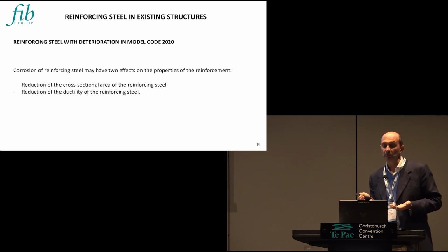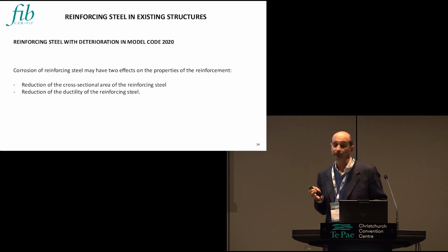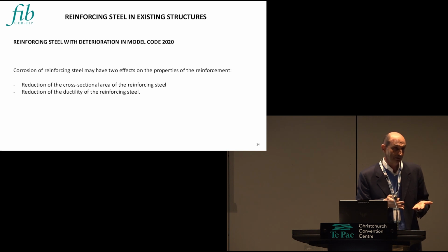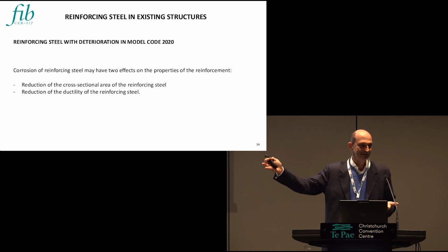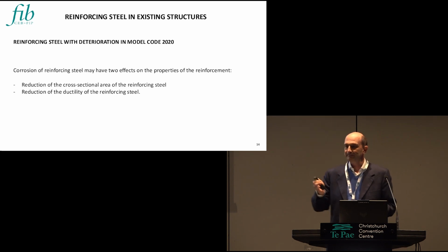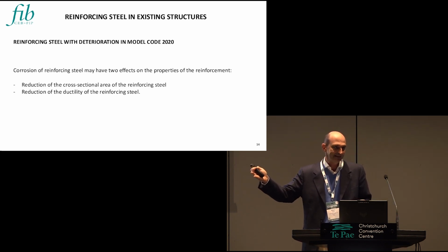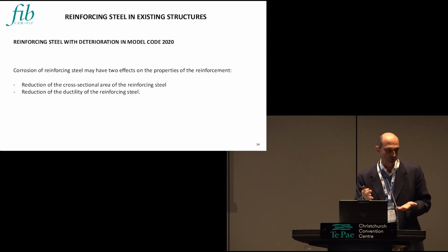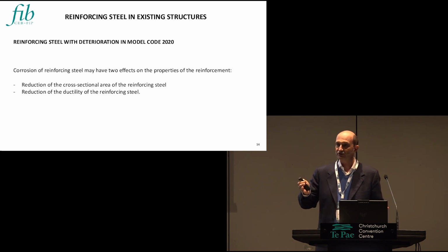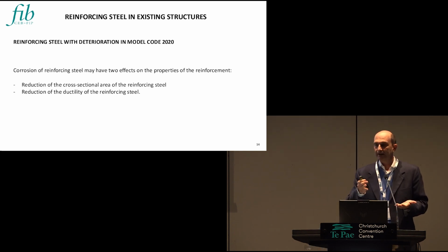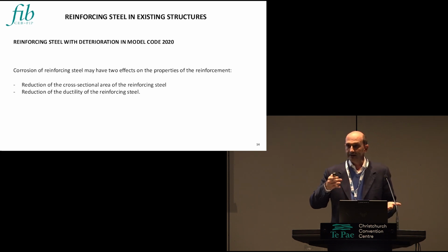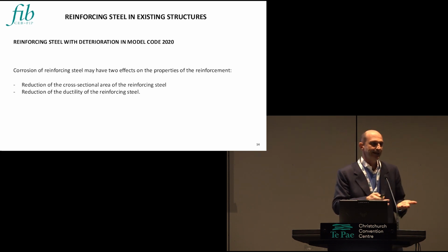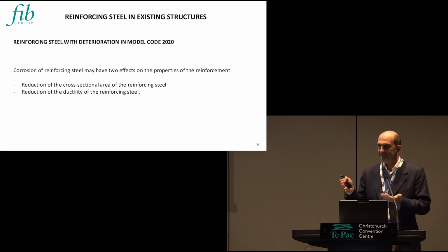And we think in a section that if we reduce the area of the steel, we have an increased ductility, because we reduce the steel percentage. But that is not true, because with corrosion, we have a strong reduction in ductility in the rebars. And that aspect could lead to a strong reduction of ductility at sectional level and at structural level.